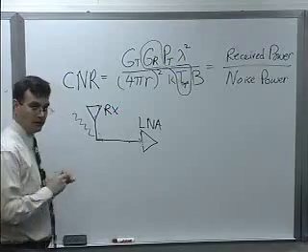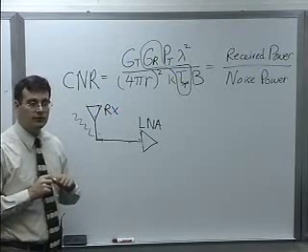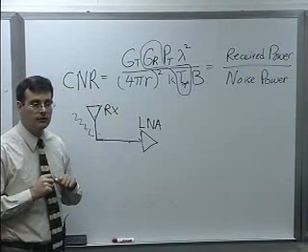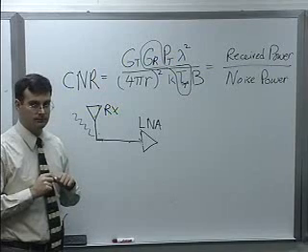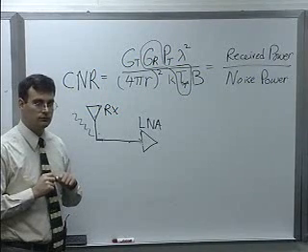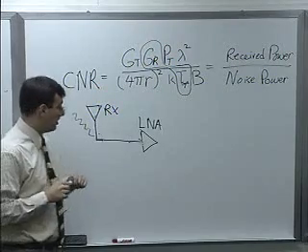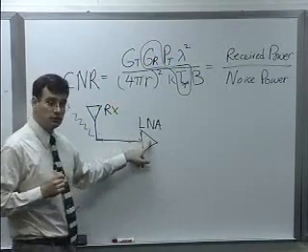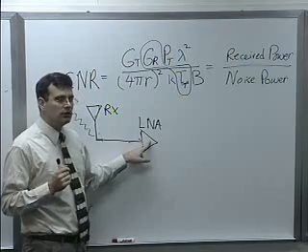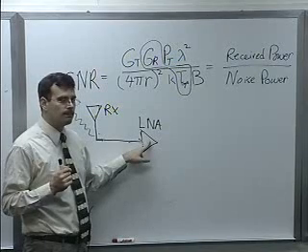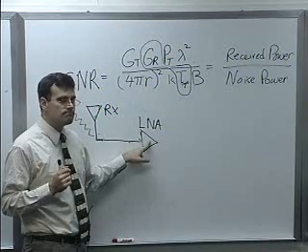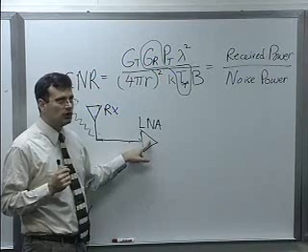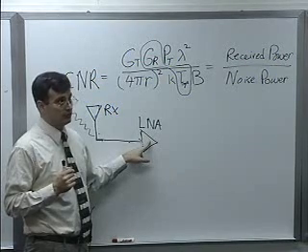But the mixer is a nonlinear operation. So if something is at 10 gigahertz and 5 gigahertz, it still can be a problem, because it can mix with some harmonic of the local oscillator and can still come into the band after the mixing. That's true. That's true.